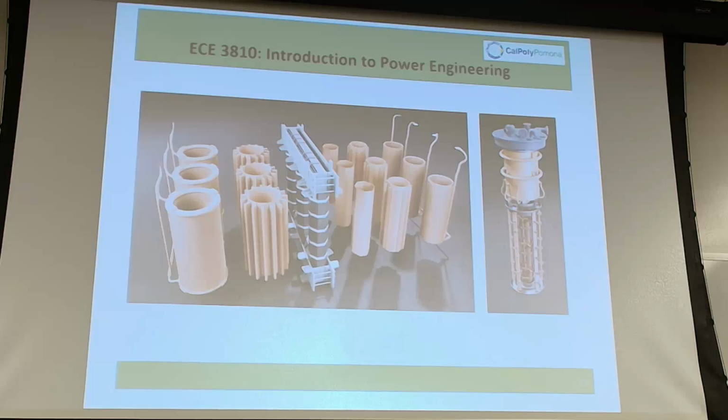It turns out this was a really nice, big factory that Mitsubishi had opened. We were transformer number 2. They left the transformer, these light parts, outside for one extra day that they should not have been out, and instead it collected moisture, and that's what was showing up.